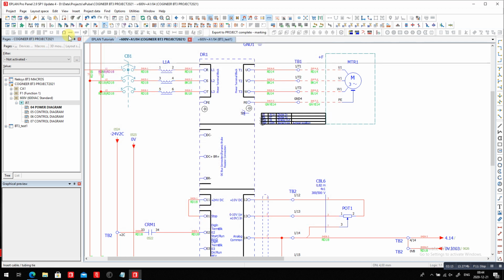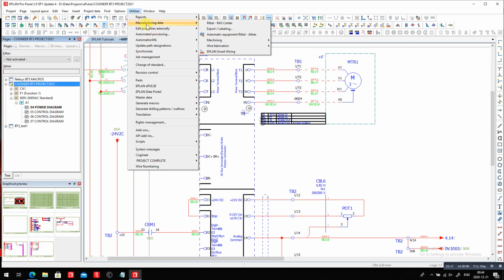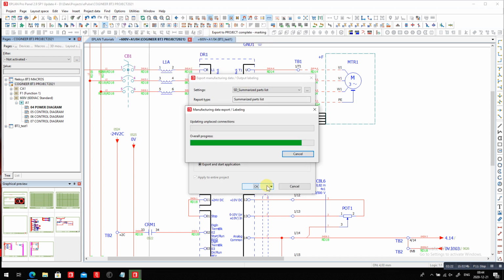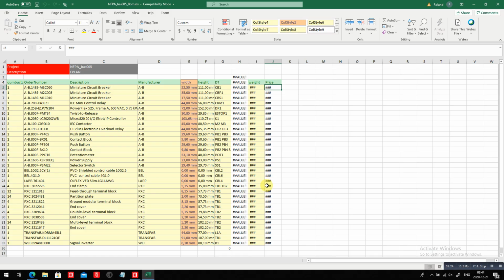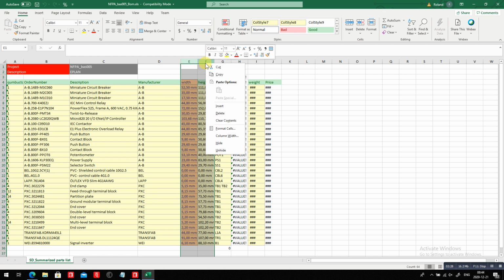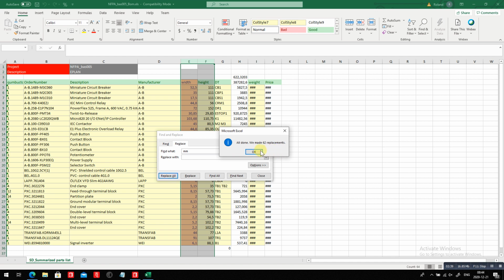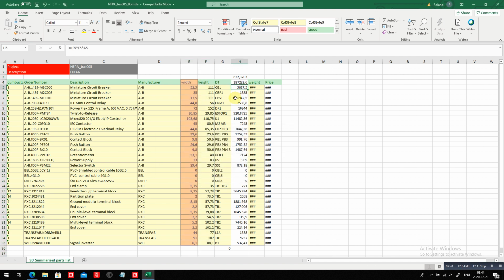So, of course, the next step is to evaluate out of this project here, how much space do I need? So I found an interesting way to calculate this. If you actually take each object, each component that is inside your panel, you calculate the width and height. Technically, the width and height, if I take these and I eliminate the mm for the millimeters, you will get a plain number, which is millimeters. And what this gives me is basically an area for each component.